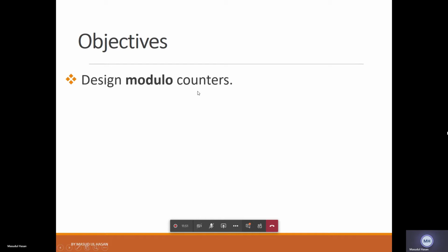This 5 can be done by 3 bits only. Why do we have a 4-bit output, right? You can think like this, because of the 7 segment. See, don't make it a 3-bit counter. Up to 5, all the digits can fit into 3 bits, right? But we are going to connect this output to the 7-segment display, and the 7-segment display needs 4 bits.